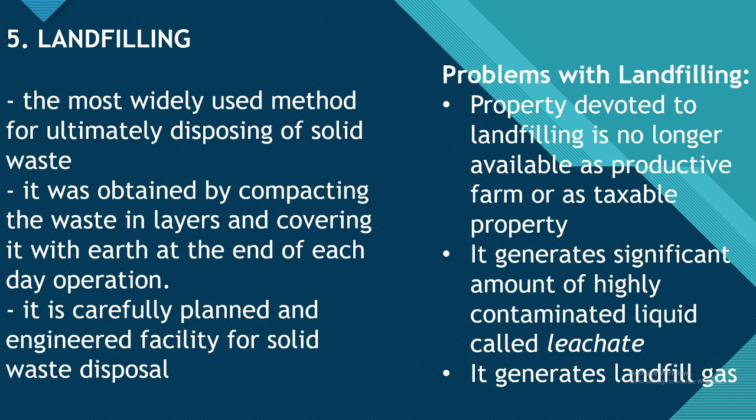Last one is landfilling, the most widely used method for ultimately disposing of solid waste. It is done by compacting the waste in layers and covering it with earth at the end of each day's operation. It is a carefully planned and engineered facility for solid waste disposal.